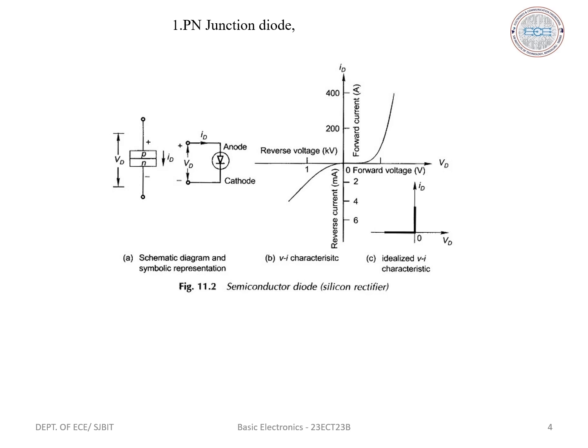The reverse characteristics is a graph of reverse voltage versus reverse current, as shown in the above figure. Current flowing through a diode in the reverse bias state is the reverse saturation current, which flows due to the minority carriers. Therefore, it is treated as a negative current. Hence, the reverse characteristics appear in the third quadrant as shown in the above figure.